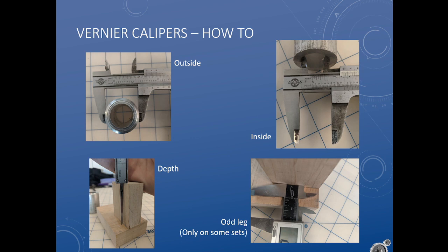I also have a thumb screw here to tighten if I want to lock in a measurement. So I can take my measurement. Maybe if I want to, again, use my depth gauge and find out the depth of this, I'm going to slide my rod all the way down until it hits the ground, lock in my measurement, and then I can read it, wander off, write it down. Your little plastic ones don't have that. That would have cost an extra $1.